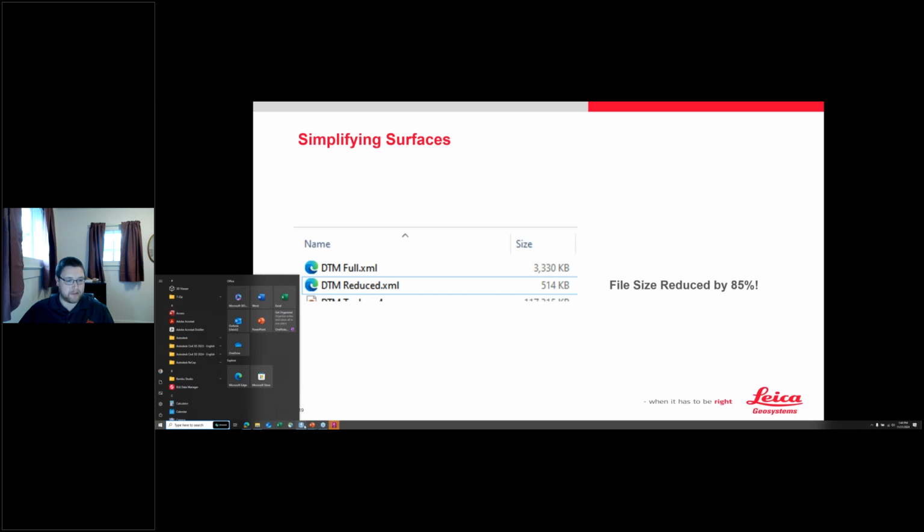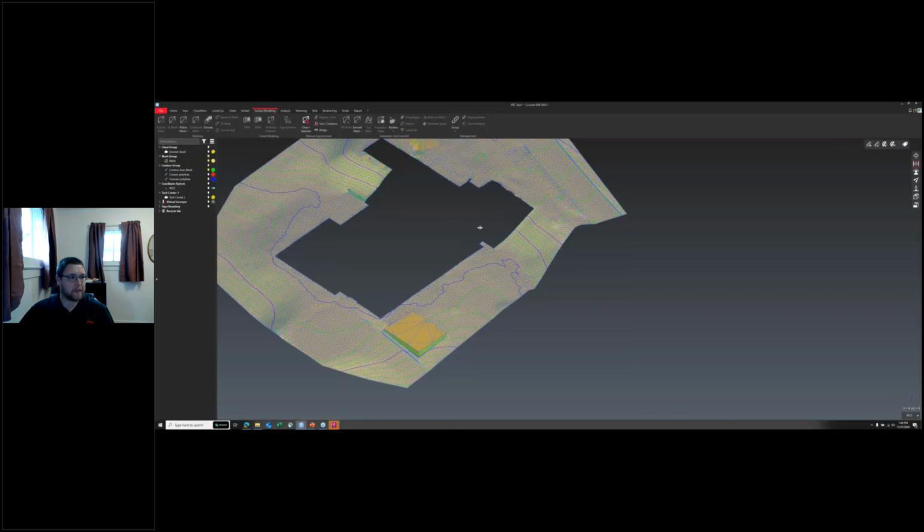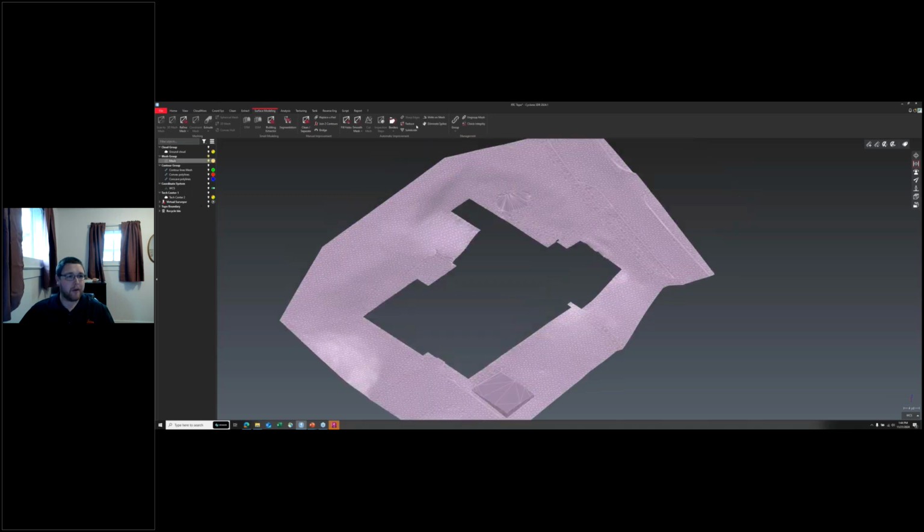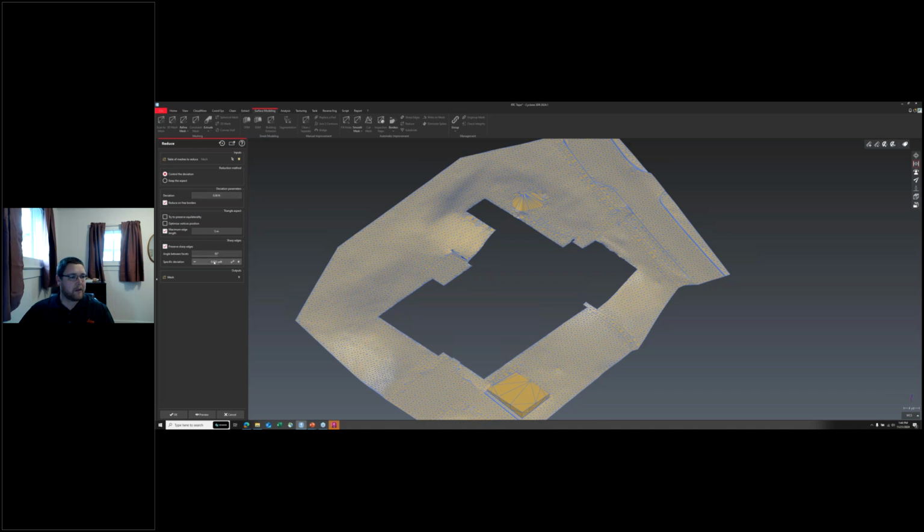So I could jump back here to this surface. I'll turn off these contours. So I'm going to run that tool right now. I'll run it on this surface we just created. Let's see, we'll go with that 400th, and then I'm going to change this down. I'm going to go with 89 degrees, because if I have that at 895, I could have some triangles that are inverted. This software doesn't care about triangles going back on itself.